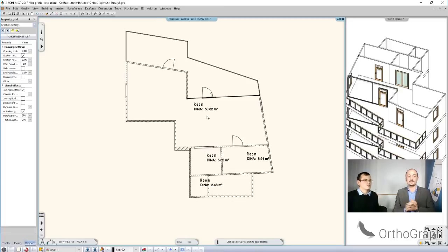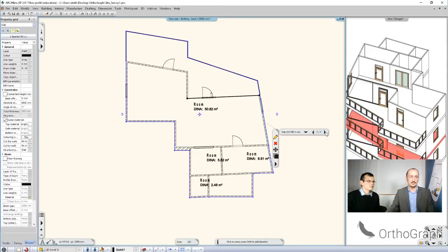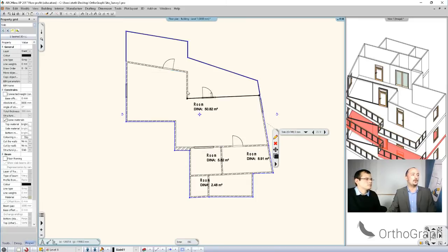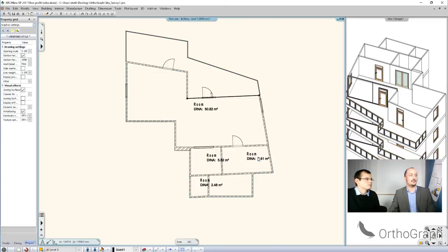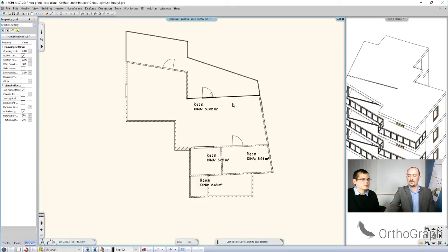You can make changes on those levels once you have had a copy. And finally, let's just add a ceiling on top of this whole structure. This will be the roof. There is a built-in roof tool as well, but I think now a flat roof will pretty much do. So I make a copy of that on top of level 3, and so now everything is just fine. So let's go back to the 2D floor plan, and then I will set up a perspective.